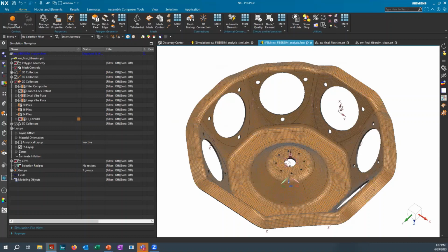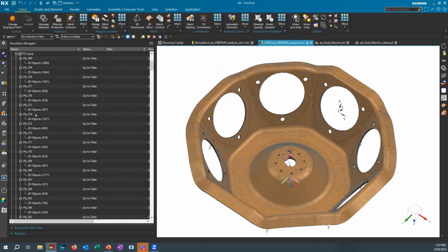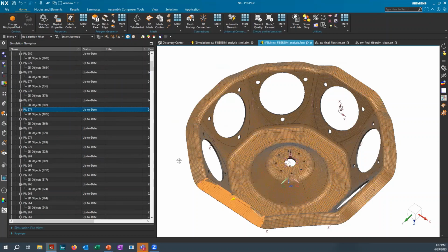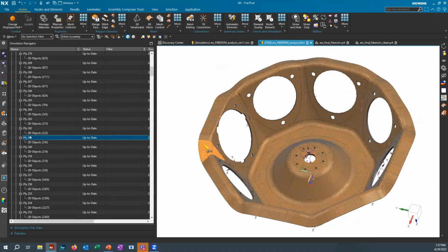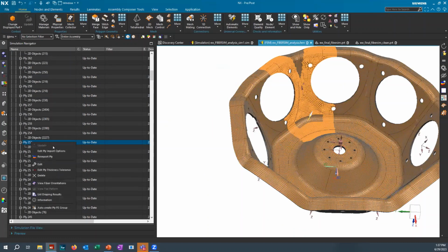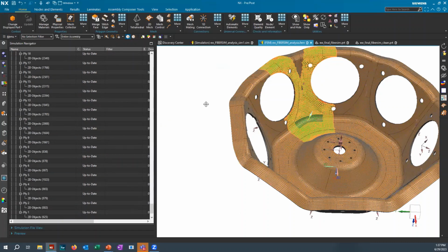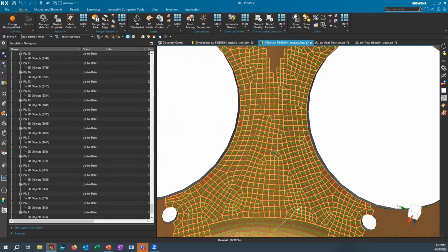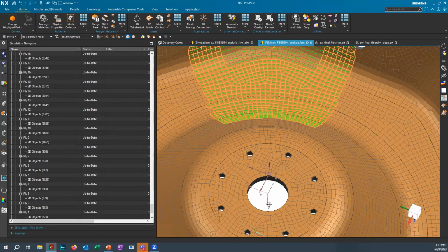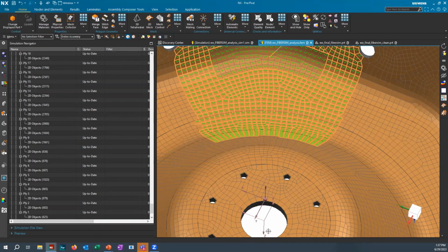The other thing we can do is take a look at the actual layups and fiber orientations. So here, let's find a little bit more interesting of a ply. Let's do this one right here. I can right click and view fiber orientations on the part. Again, this is the data from the Fibersim model for this particular ply. Using a radial rosette, this is probably a 45-degree ply.